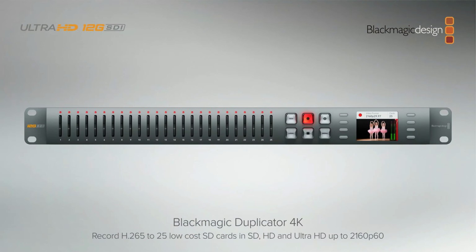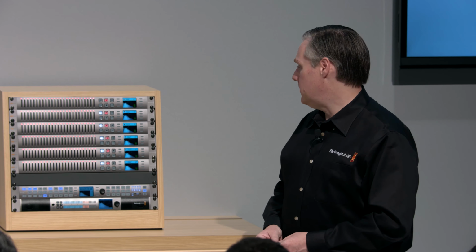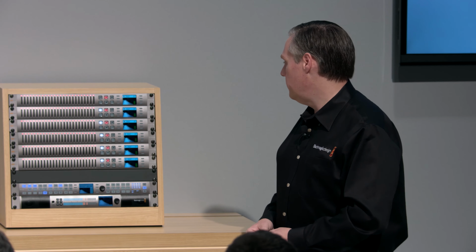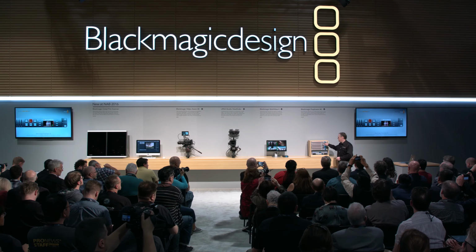It's got some control panel buttons on the front, and then you just plug the cards in. You pretty much just hit record. It's a 12G SDI device, so it handles all frame rates up to Ultra HD 60p. The compression format is H.265, which is designed for Ultra HD, so the data files are not that much bigger than HD files are.